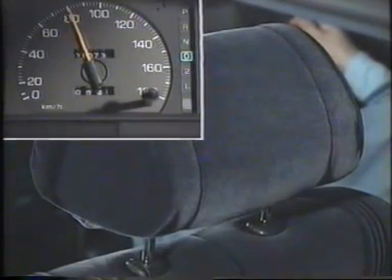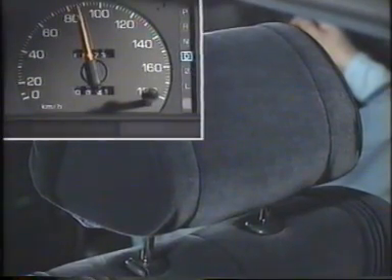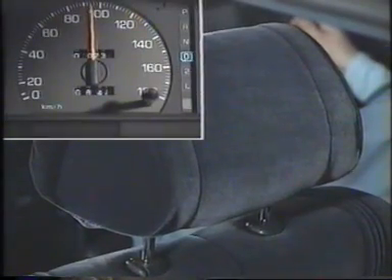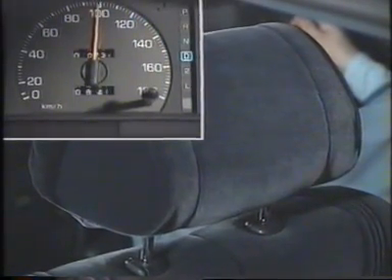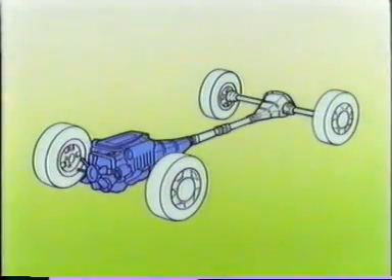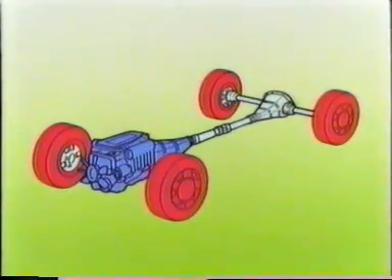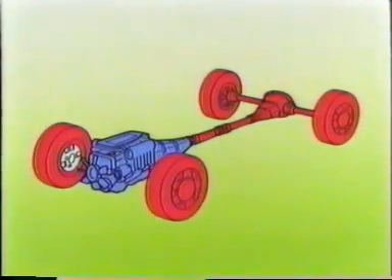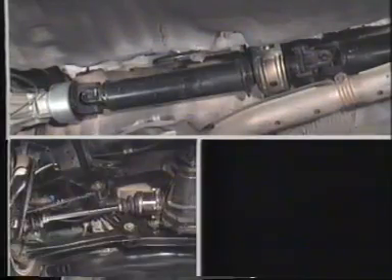We know that the vibration increases as the vehicle speed increases. It appears then that you should suspect a component whose rotational speed increases as the vehicle speed increases. It could be the propeller shaft, the differential ring gear, the drive shafts, or the tires, or some combination of these. The next step is to find out exactly which of these components is responsible for the problem. There is a good way to identify this component.